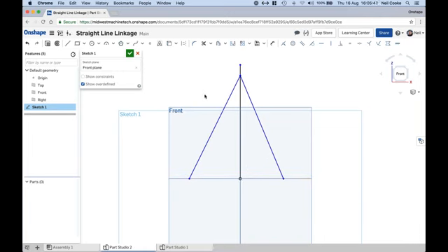Now, what I'm going to be doing a lot during these sketch creations is using the equal constraint, because obviously I am representing here the same linkage, so therefore they should all be the same length. So I'm going to select all these 3 guys here and use the equal constraint, or I'm going to be using E on the keyboard just to make things a little bit simpler.